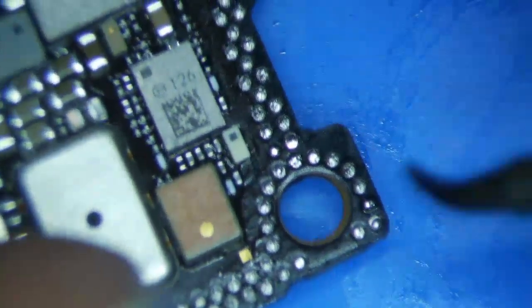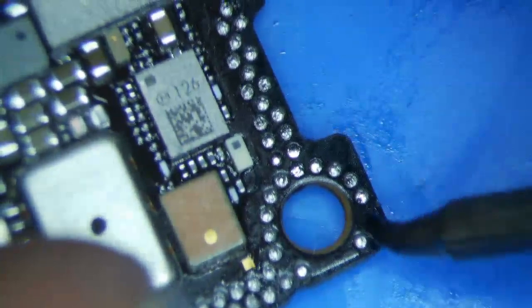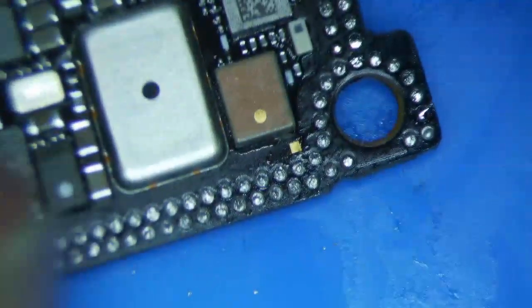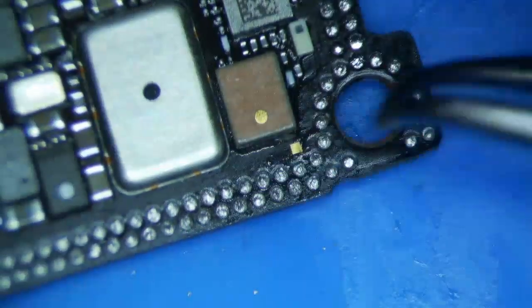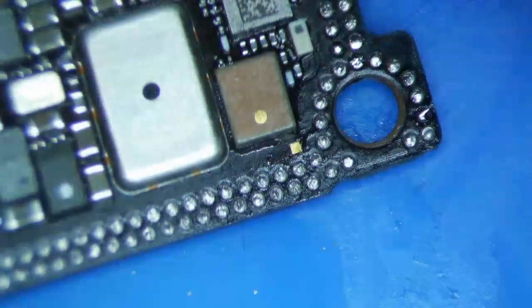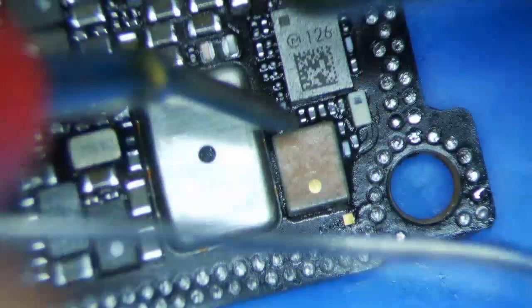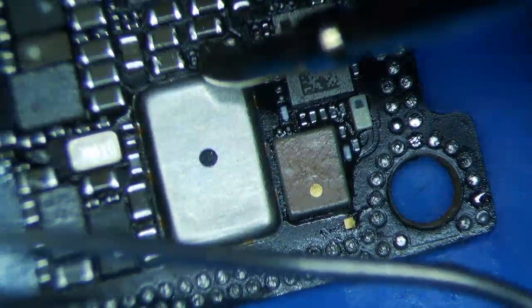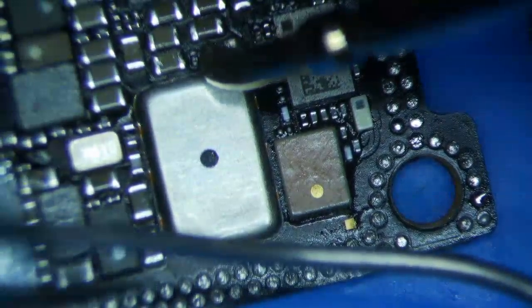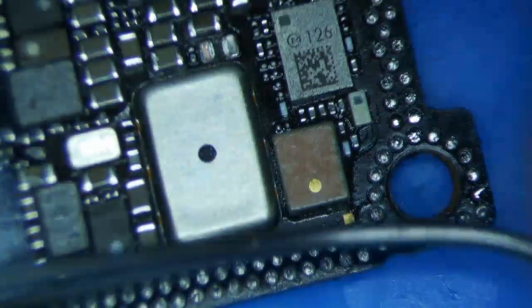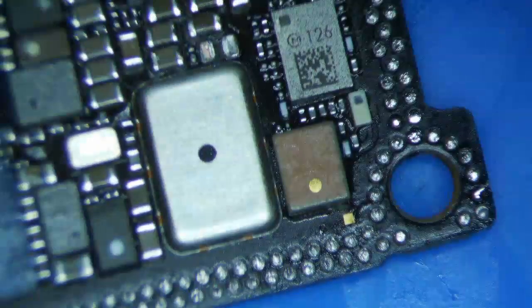Okay, not too much solder, otherwise it's going to bridge, especially these round pads. Okay. God, this is the hardest part right here, getting all this back together. Okay, so get all the lint. Not mandatory, but probably better. Before we forget, let's just test this, just to make sure that the short is gone. .379 volts. Okay, it's gone.